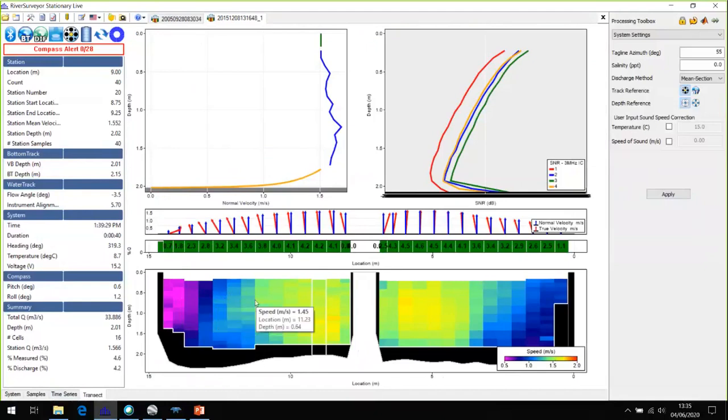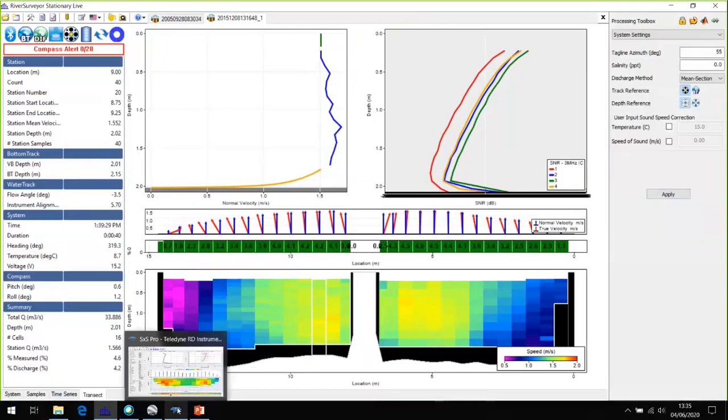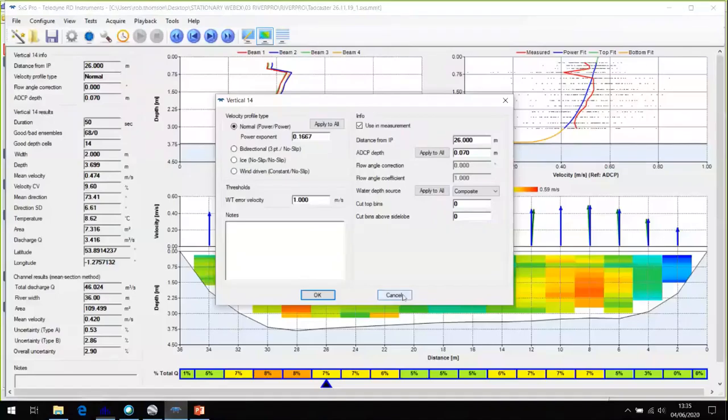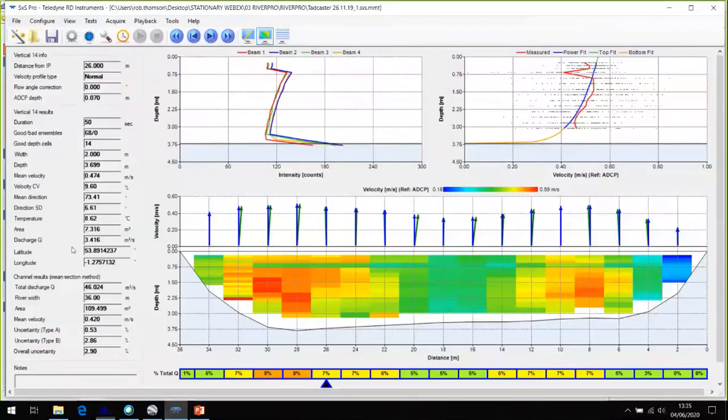These can be sort of every 2 meters if it's a channel like this, but they should really reflect flow and also the geometry of the bed, so this should be sort of irregular. It's based around ISO 748. So if you think around your ISO 748 and how you would apply that for a wading measurement or a point velocity measurement, that's pretty much what it's trying to do.